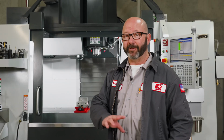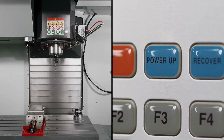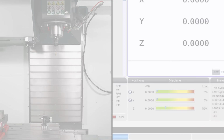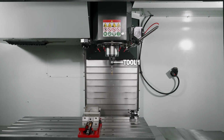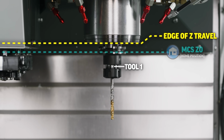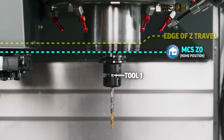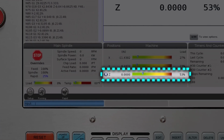If you run mills every day, you might have noticed that after turning on the machine and pressing that power up key, the Z home icon is not always displayed. This will happen when the machine has been shut down with tool 1, T1, already in the spindle. No tool change at power up to T1 was needed, so our machine comes to rest at the edge of our Z travel, which we know is not our Z home. In this case, pressing the power up key a second time will move our Z from the edge of travel down to our tool change position, which is our Z home position.